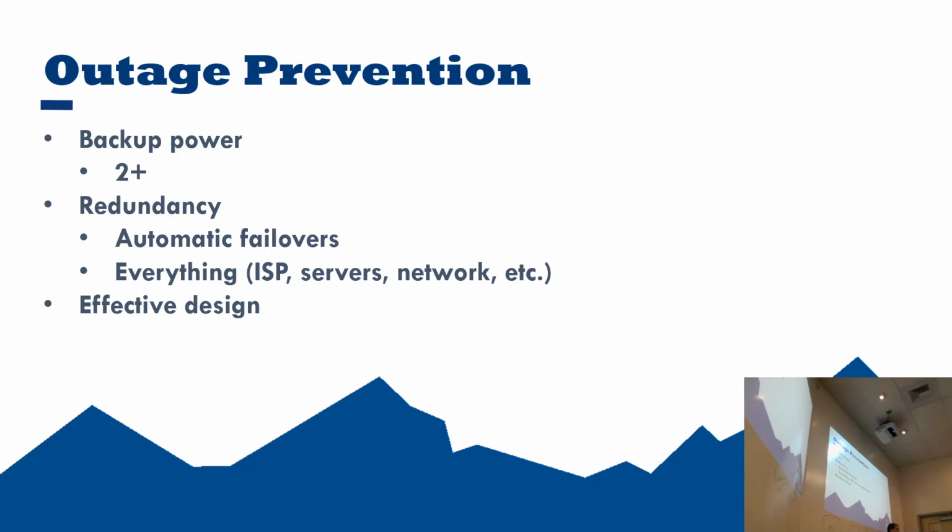Extremely heavy. All right. So if you put those on anything other than a ground floor with like a slab foundation, what's likely to happen? Break the floor, exactly. So batteries, in my opinion, would not make a good outage prevention. Not to say you shouldn't consider UPSs for server racks and that sort of stuff, but I would recommend against them for an entire building.